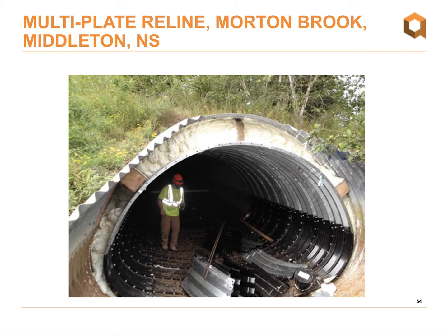Here you can see the structure with the polymer foam in place. You can also see the blocking which was placed to prevent flotation and movement. You will see there's a considerable void at the crown of this structure. Of course, with a reline, the largest the new structure can be is smaller than the host pipe at its narrowest point. This structure had deformed considerably, and the size chosen was necessary to clear the host pipe at all points. The customer is responsible for providing the survey or sizing data which we will use to suggest the best possible shape to maintain the maximum amount of end area.